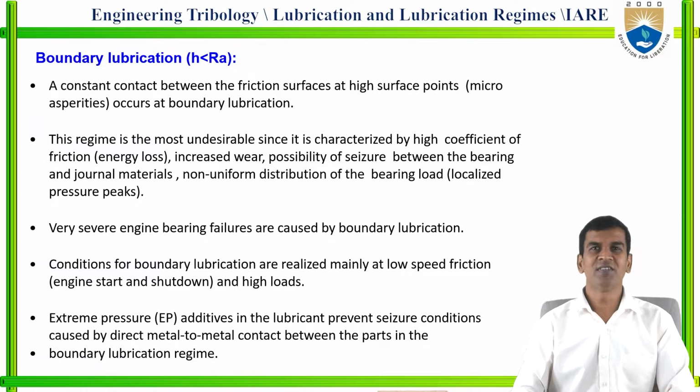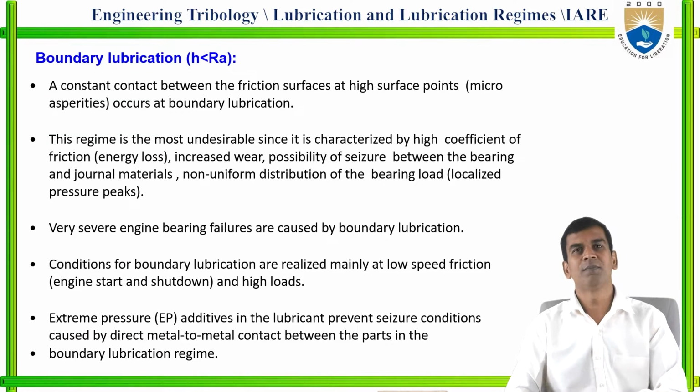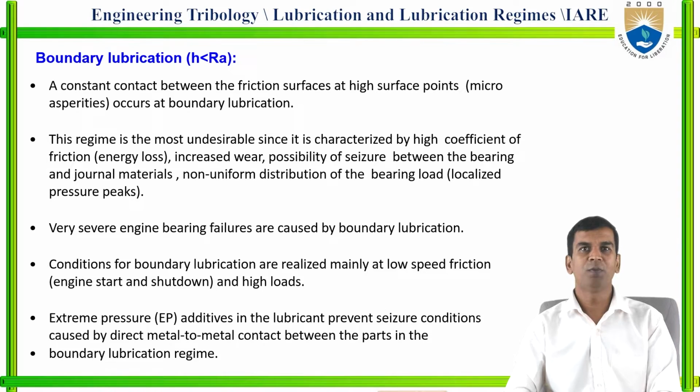If h is less than Ra, nothing but the thickness is less than the roughness, then we will call it boundary lubrication. In boundary lubrication, constant contact between the frictional surfaces occurs at the high surface points.